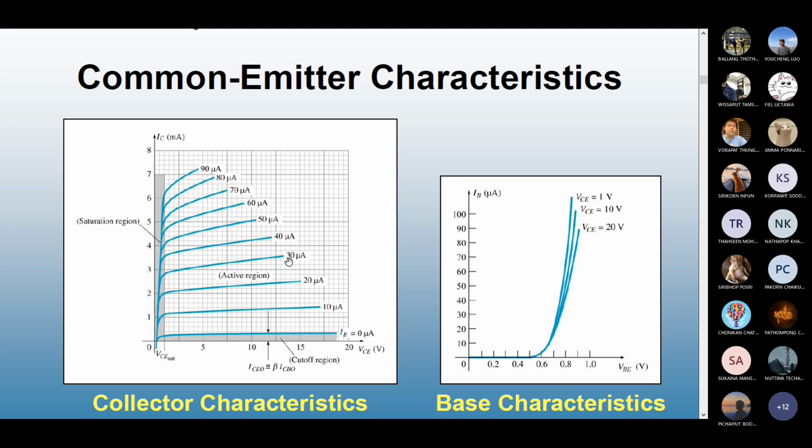Let's say you find out by calculation that your IB is 20 microamp. So you have to do all your reading from the 20 microamp blue line. You can also remember that in the last topic we taught load line. What is the load line? The load line is the black line that is decided by the network by using two extreme points.